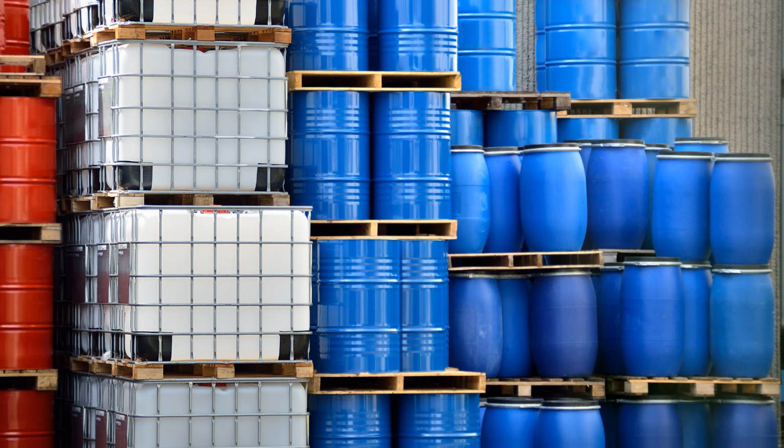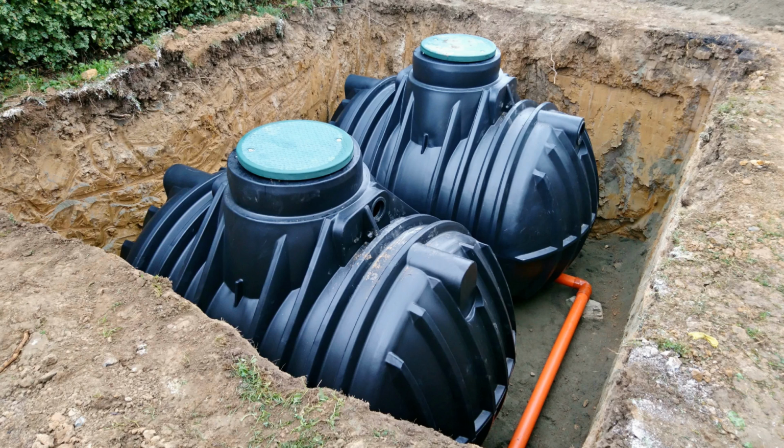Storage areas and containers should be inspected regularly for spills and leaks. When new containers are purchased, check for loose fittings and poorly welded seams. Tank foundations, connections, and piping should also be checked for spills, leaks, and corrosion. Underground storage tanks must be regularly inspected for leakage, and it is helpful to install alarms for underground storage.